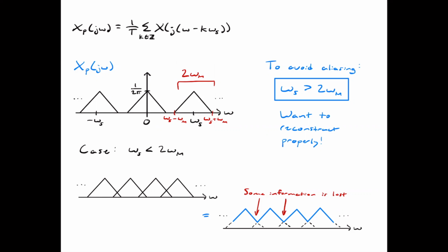recover our original signal. The sampling theorem states that we must sample fast enough such that all the information in the signal is captured. This means that our sample frequency must be at least twice that of the highest frequency component of the signal. If this condition is not satisfied, then the shifted copies will overlap, and aliasing effectively kills the overlapping parts of the signal.